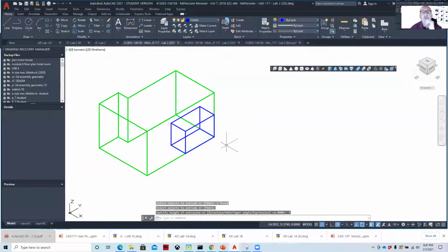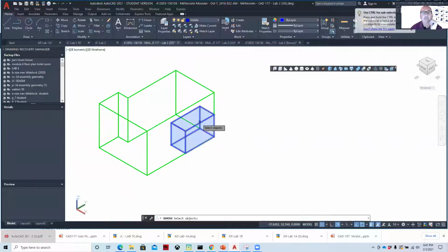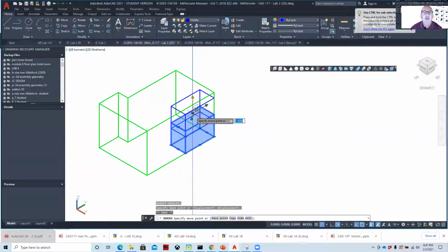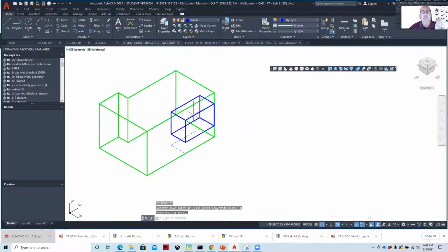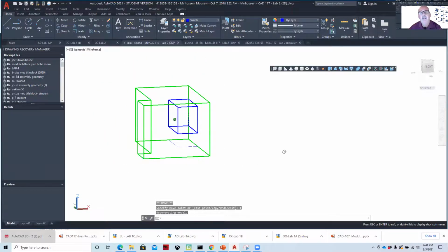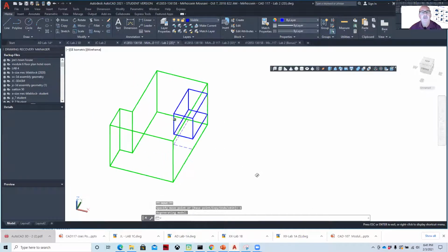And then I would move it. And so you can 3D move it. Grab the rocket and move it up 1 unit. Let's see. Yeah, 1 unit in the Z-axis. And it'll track in the Z-axis. And so that's where it goes in the part. Now I realize I've been doing this for a while, so I'll show you a second way to do this. Let me copy that.